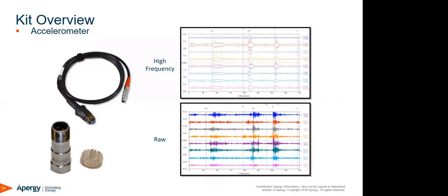It's important not to drop the accelerometer or just slap it onto a test point. Also, you want to avoid overheating the sensor itself. A general rule of thumb for accelerometers: if it's too hot to touch, then it should be cooled down before taking data again.